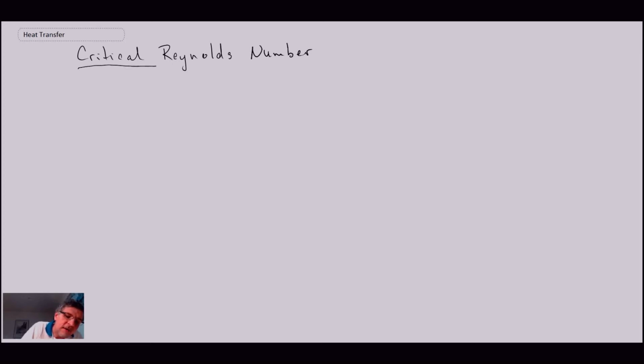There's a field called hydrodynamic stability, and that is involved with studying the process of transition from laminar to turbulent. But as a rule of thumb, 5 times 10 to the 5 is the number that you'll often see quoted in the literature.